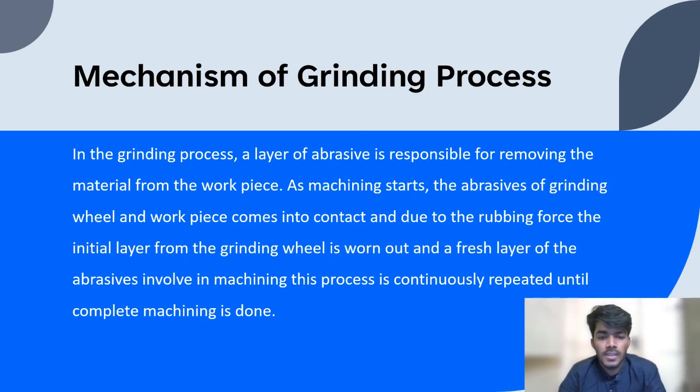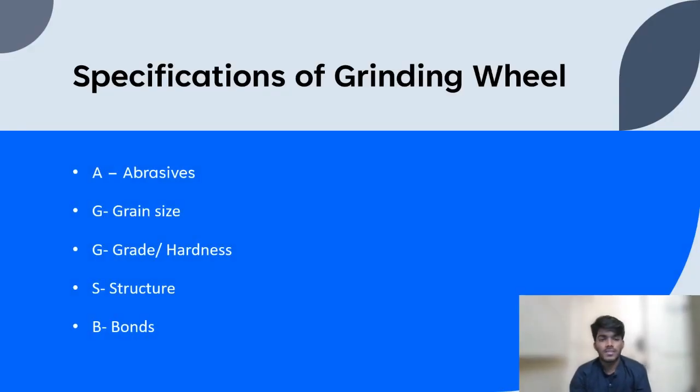So now let's see about the mechanism of chip formation in grinding process. The mechanism of chip formation in grinding process involves high speed interaction of abrasive grain and the metal, which leads to concentration of thermal energy in front of the deforming element, that is the grain, causing a locally concentrated shift in metal microvolume. In abrasive grain metal contact, a dissipative structure is formed whose existence is supported by exchange of energy and substance with the environment.